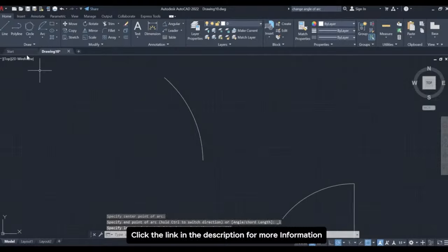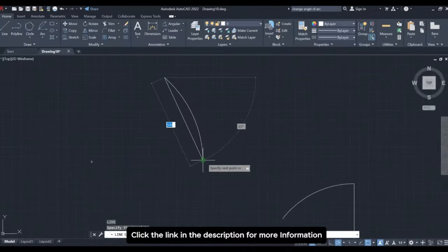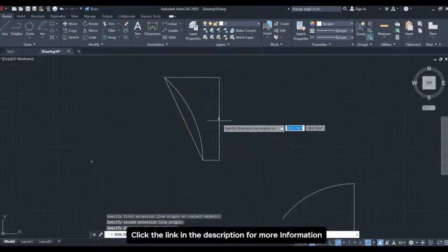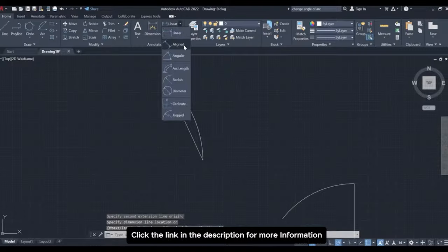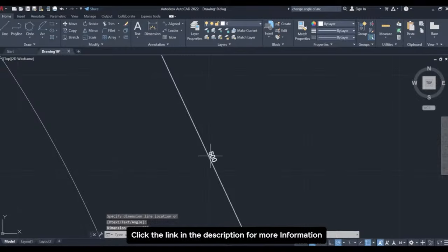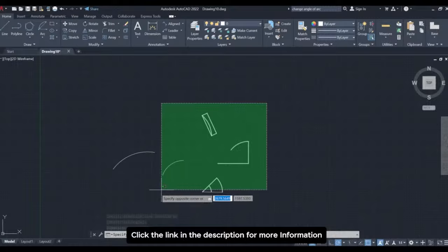In this case, if I were to draw a line from this point until here, you'll see that it already shows up over here to be 500. But either way, I click on it and show you that the length in the linear direction for this particular line is 500. All right. So those are arcs.